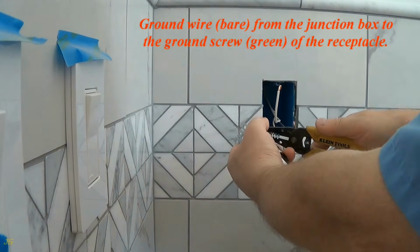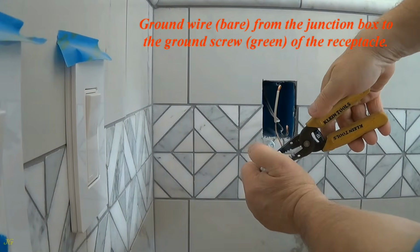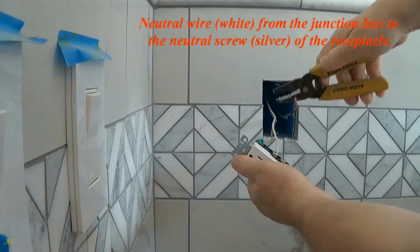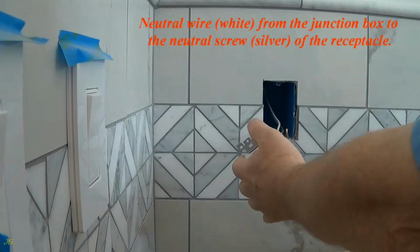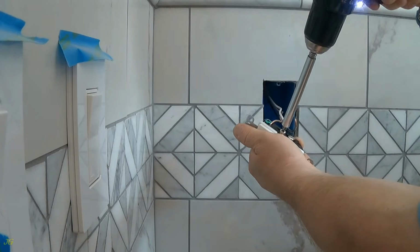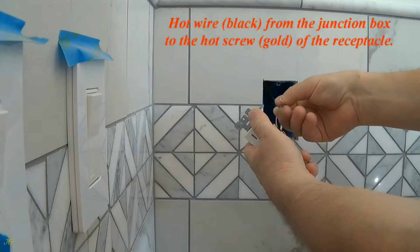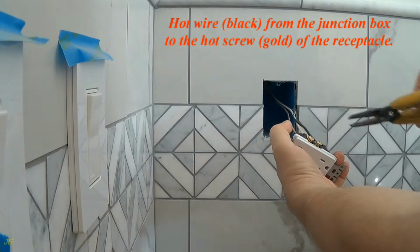Ground wire, bare, from the junction box to the ground screw, green, of the receptacle. Neutral wire, white, from the junction box to the neutral screw, silver, of the receptacle. Hot wire, black, from the junction box to the hot screw, gold, of the receptacle.